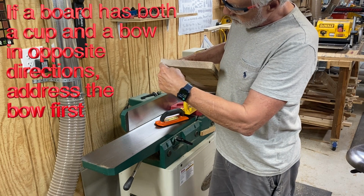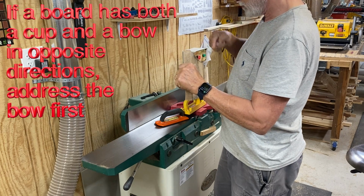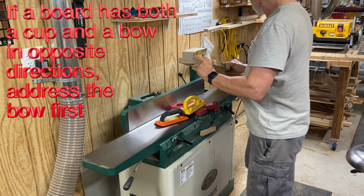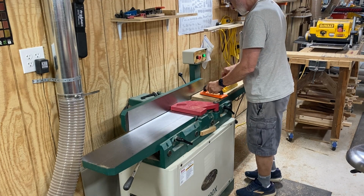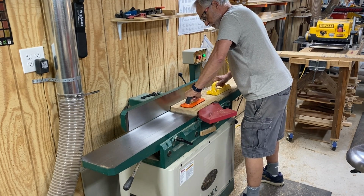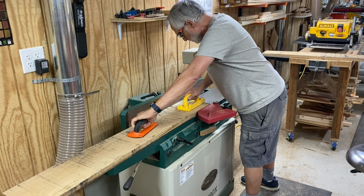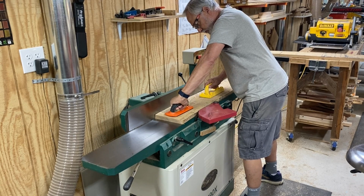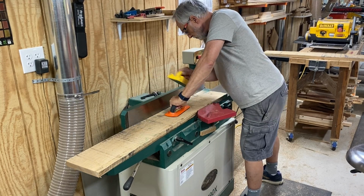If the board face is cupped and or bowed from end to end, place the concave side down to keep the outside edges or ends in contact with the table. Turn on the jointer and using push pads, never your hands, apply light downward pressure against the infeed table as the leading edge of your stock crosses the cutter head. Transfer downward pressure to the outfeed table immediately after passing the cutter head. This is important since the outfeed table is level with the cutter head, so the outfeed table becomes the reference face that you're jointing to.